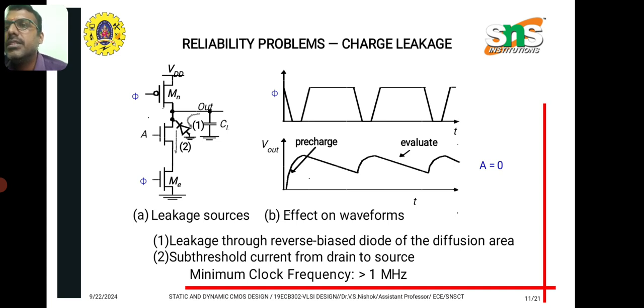If you consider n number of input variables, then due to parasitic capacitances, the charge starts to be shared from the output path. Due to that, there will be a degraded output. So that is also a main drawback here.